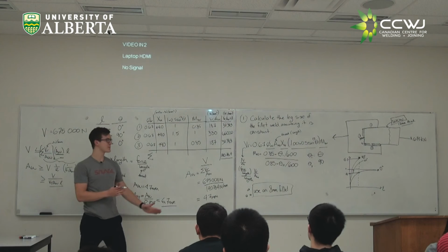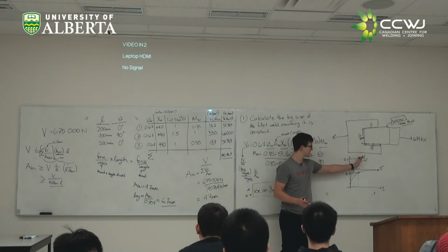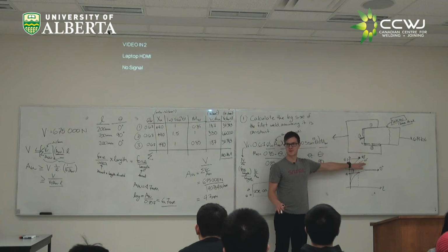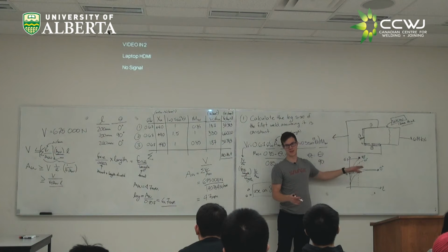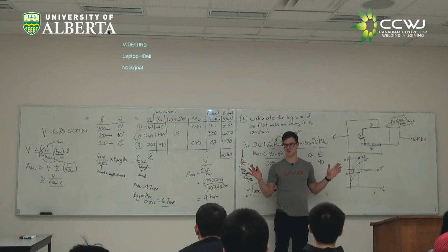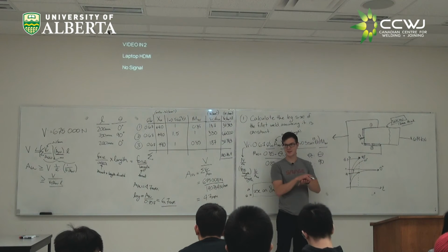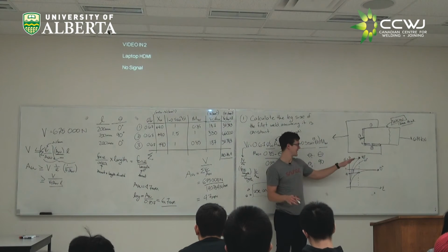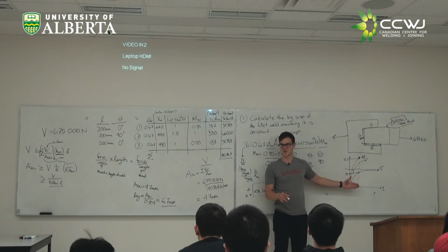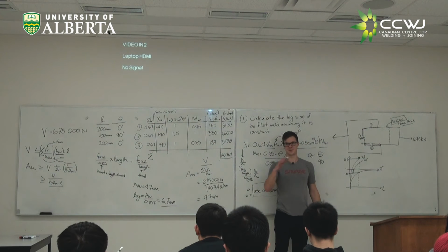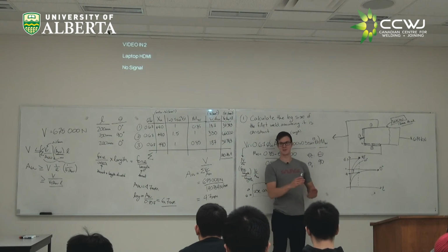It's a little bit more complicated than that. What we're saying is this is the point where we consider our structure to have failed. What happens beyond this point becomes a question of how this fails, whether it fails plastically, whether it fails by fracture and just disappears. We don't worry about that. If you were to say at this point the whole weld instantaneously fractures through, then we would consider our structure to be failed because all the load would be transferred to this weld, and we're assuming that it's now not going to be able to support that load. But we're not going into those details.